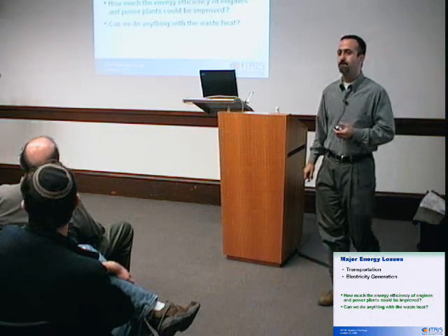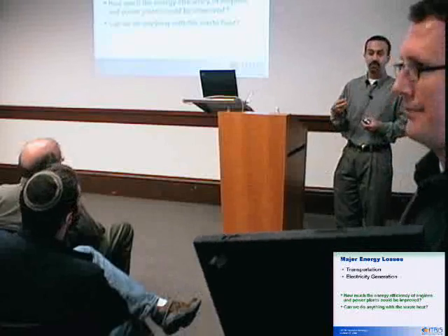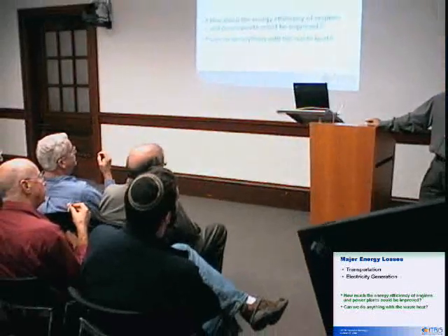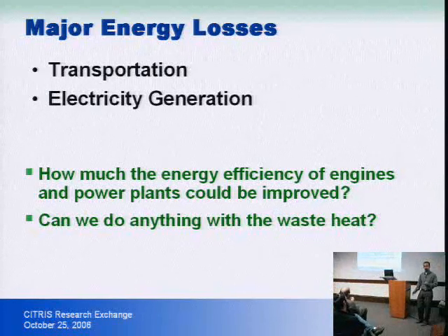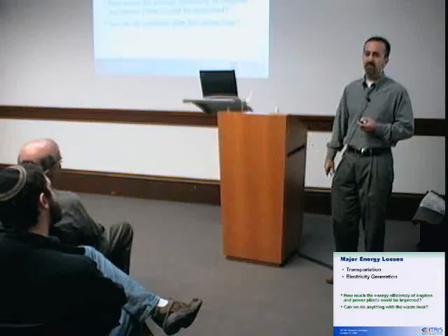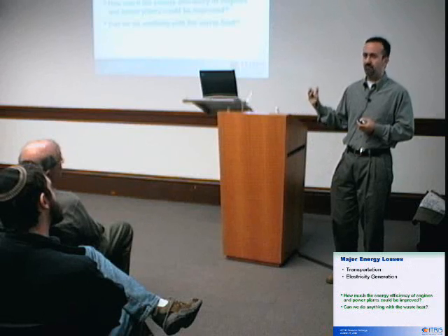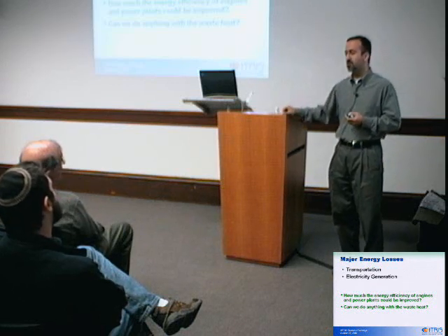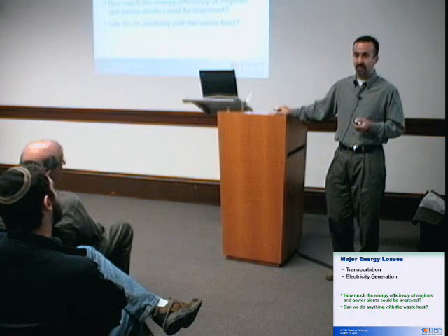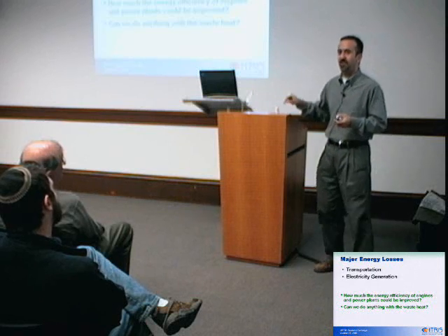Yes. So if we all had cars that we plugged into the wall, would it be a 10% net improvement? That's actually a good question. If you look at it, the energy efficiency of electrical cars compared to diesel engines is definitely better on the electrical cars. The main reason is how you accelerate and decelerate. But I haven't seen a clear analysis. But just to give you an idea, typically our best power plants have an efficiency of about 50%. And you have all these issues. Most of our loss in the electricity is at the generation and not in the transport, but also in the storage, because we don't use it all the time, the uniform amount. That's a huge cost to store it. And the cars are about 20 to 30% efficient. So there is somewhere there that you could gain, but it's not a huge gain that you can have.